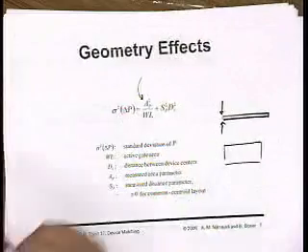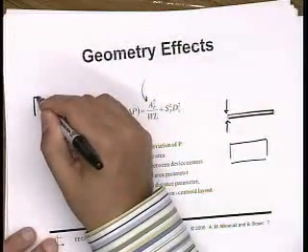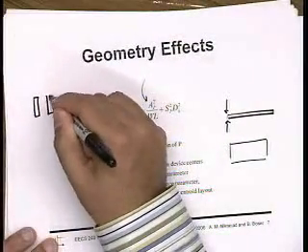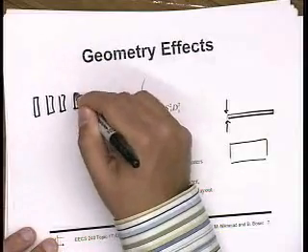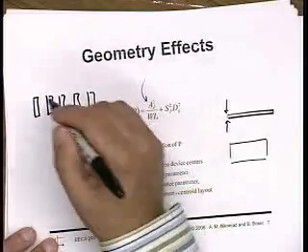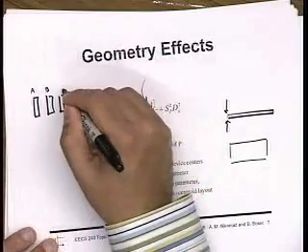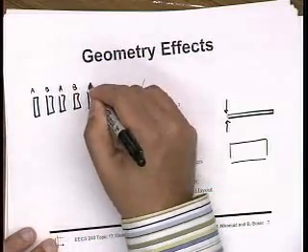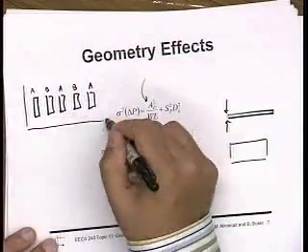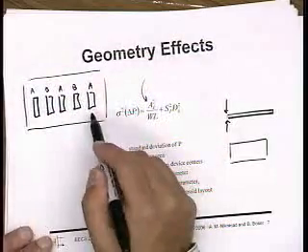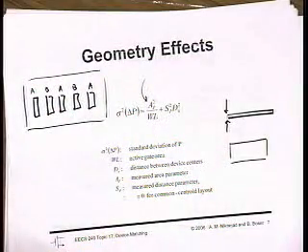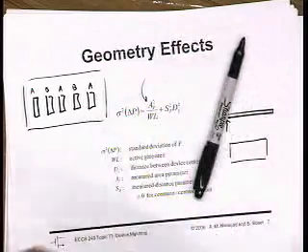Your argument is that I'm going to lay out my device like this, right? And this is device A, this is device B. Usually, and we're going to talk about this more towards the end of lecture, if I have a fingered device, I can actually improve the matching, because I can now intermingle my devices.